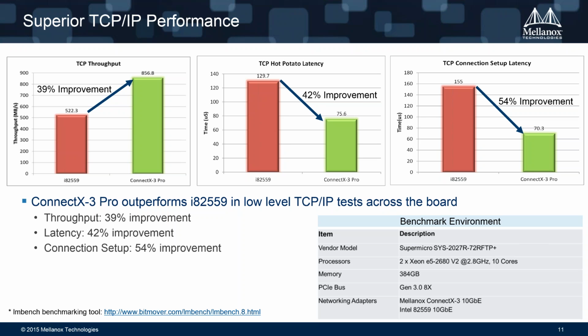Mellanox is unique and pretty much leads the market with what we call the offload engine, where all stateless offload tasks can be done in the silicon itself instead of using the CPU and the operating system to run the jobs. Once you have a more efficient implementation of the protocols, meaning you can use hardware offload, then the overall latency is lower and the overall performance is higher.